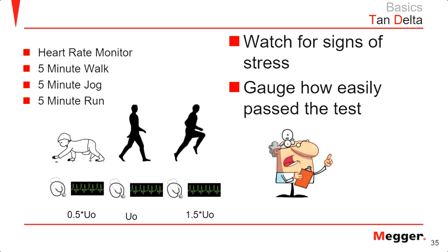Whenever you find that weaker cable, that allows you to know the life expectancy of that cable. It is ultimately up to you if you want to replace the cable, but all it's telling you is your life expectancy. Are you noticing that there is something that is growing within your cable or not? So if you're the owner of that application and you're doing it during a maintenance time and you feel that it's time to replace that cable and you have the resources to do that right then and there, then I would say do it.